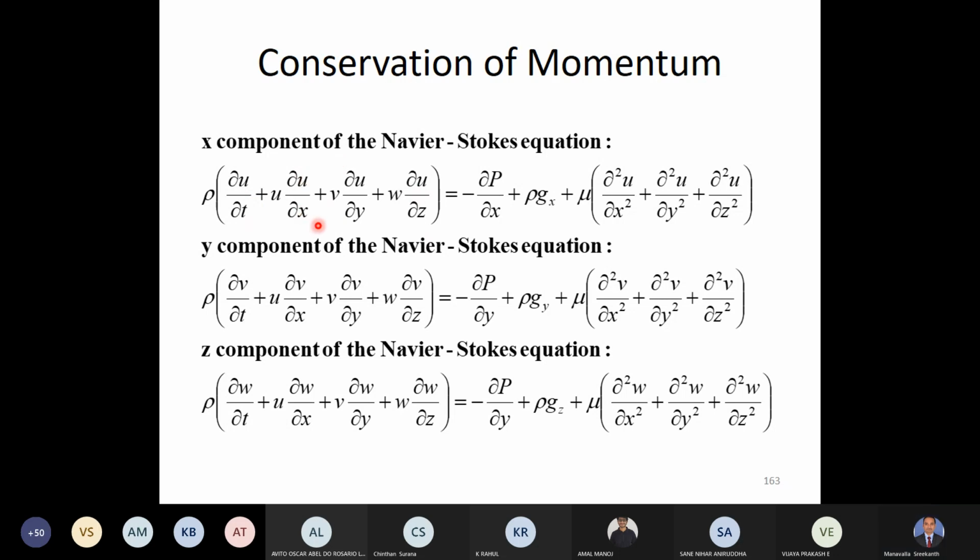And this together multiplied by rho will amount to the momentum. Okay, or the force because of the momentum. Rate of change of momentum is force. Now you see here on the right hand side, we also have some terms. Dou p by dou x is the pressure term, and rho g is the body force, and this one is the viscous force. Viscosity is here, this is the viscous force.